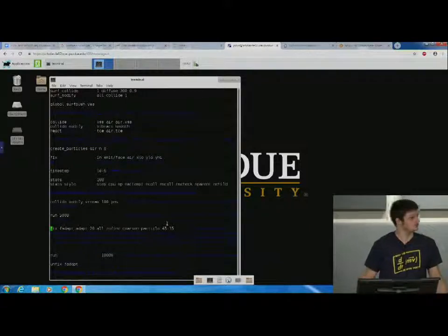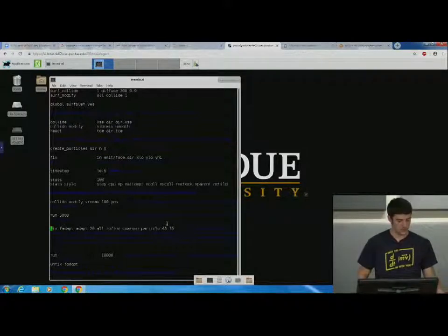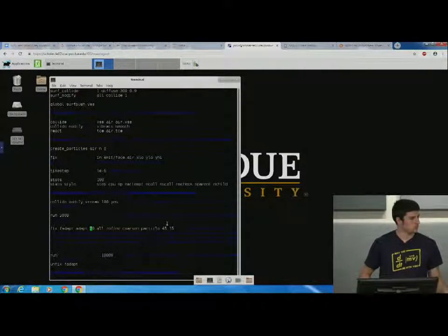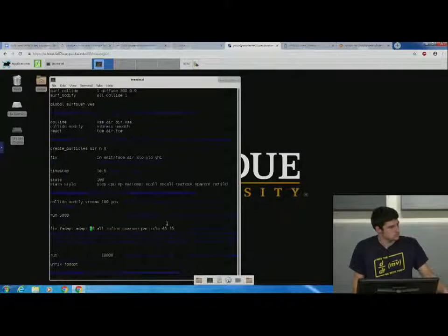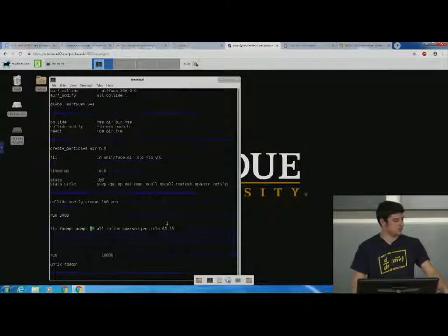Sorry, I think I missed it. What does 20 mean there? Every 20 steps, you start refining. Okay. But you don't say how. You mean what criteria I'm using to refine the mesh? Like, how are you going to determine the new size of the grids? Basically, it does it automatically, and it just does it according to other surrounding cells. So it tries to merge the cells. If it splits, I believe it just splits it in half. Okay. So it's kind of limited in that sense, but it's still better than nothing.